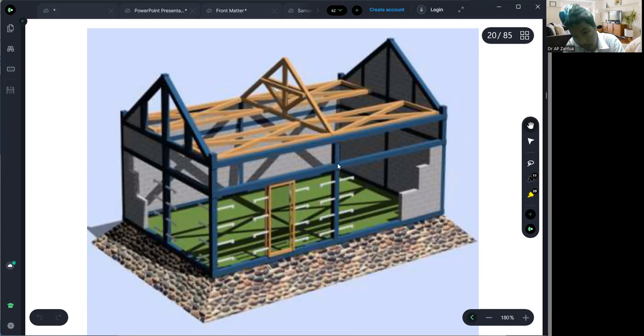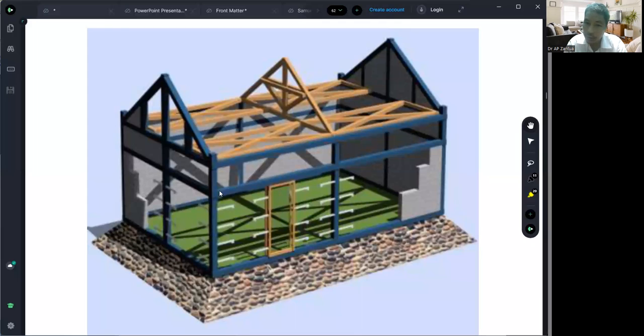Look, there is a tie beam, but at about 1 to 1.5 meters, there's another tie beam here. Okay, it is a good design. This tie beam is to support the doors and windows later on. There are windows here, so this tie beam will support those. In real design, there is usually no tie beam here, only a tie beam on the floor level and one on the roofing level.